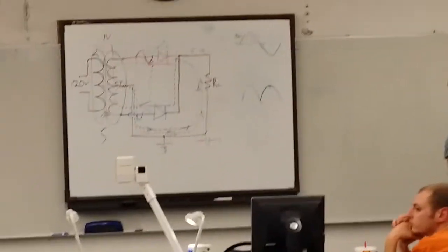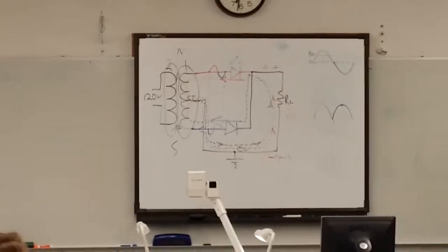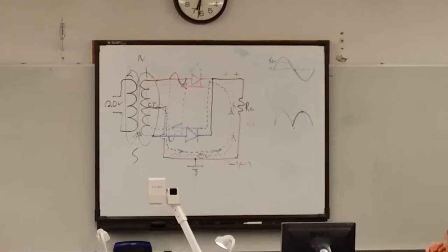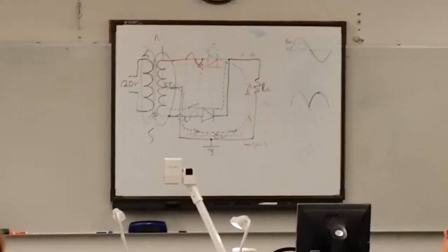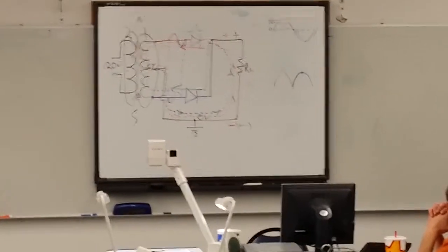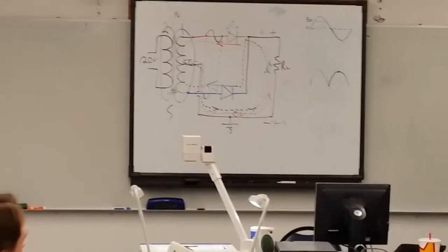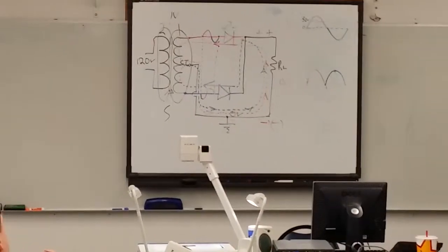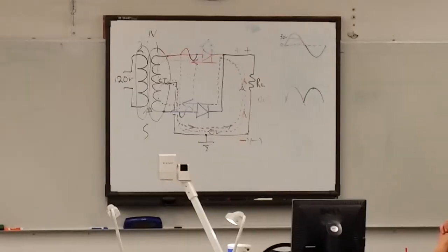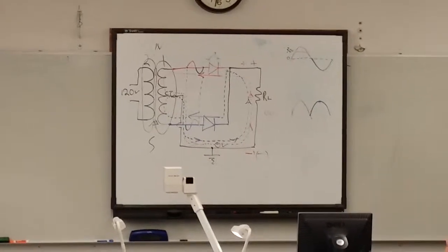So if you only flip one of them around, it would give you 2 negative pulses? If you flip one of them around, you're gonna have a direct short across the transformer, the secondary. That's what it is. It'll vibrate and hum and smoke and burn. It wouldn't work if they were two separate directions.